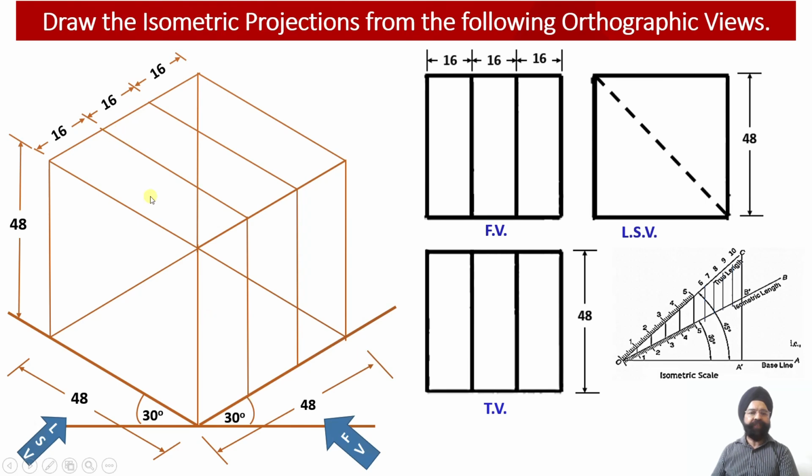So how did we derive this information? Because in the left side view, we can check that there is a dotted line or a hidden line. The hidden line corresponds to the surface of this middle web, which is an inclined web. The inclination is such that it starts from the top portion of the rear face and moves down to the bottom of the front face over there. So this is going to be an inclined web.